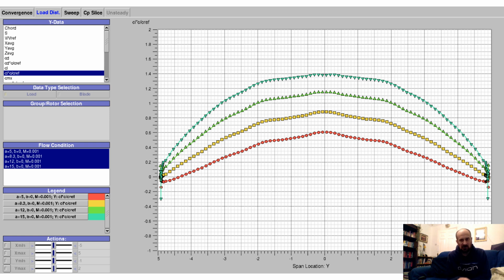But actually, when you do look at it in detail, it's still a long way off a perfect lift distribution, even with the VG tight. And of course, with the VG full tight, you've got that compromise in that you stiffen up the handling an awful lot.